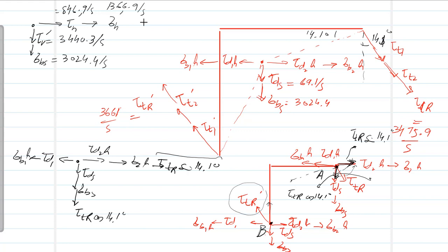Just find the resultant of these two. So the resultant of shear is tau r and the bending is sigma b, and that will be simply, for a right angle triangle, just find the hypotenuse.